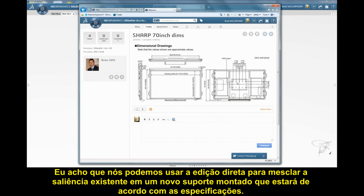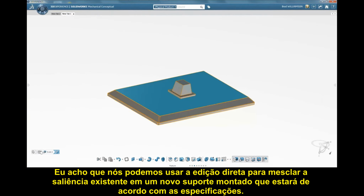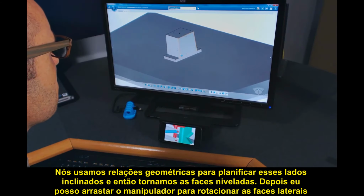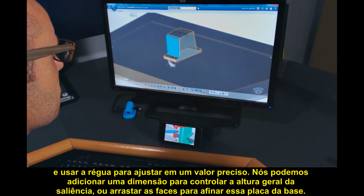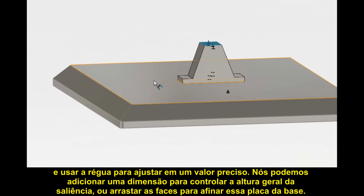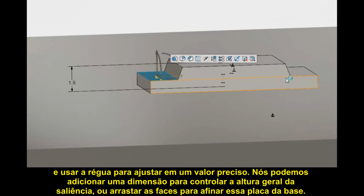I think we can use direct editing to morph the existing boss into a new mounting bracket that will match the spec sheet. We'll use geometric relationships to flatten these drafted sides, then make the faces flush. Next, I can drag the manipulator robot to rotate the side faces and use the ruler to snap in a precise value. We can add a dimension to control the overall height of the boss, or drag faces to thin out this base plate.